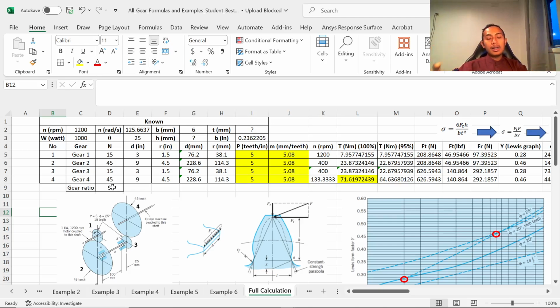I got first winner in a creative design competition in Indonesia, where we made an emergency portable charger product. We converted the high torque and low velocity from hand power into high velocity and low torque for the motor. The motor generates 5-volt electricity, enough to charge your phone in an emergency.